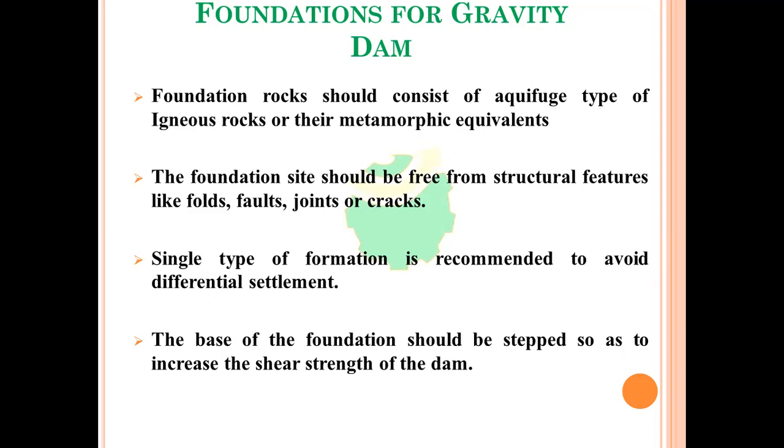The base of the foundation should be stepped so as to increase the shear strength of the dam, because the foundation plays a very important role in the strength of the dam, because at the foundation uplift pressure acts more.